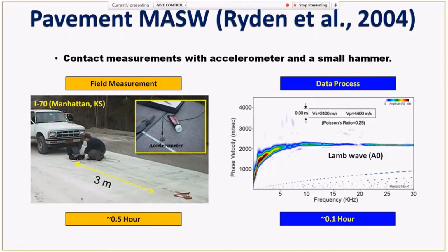So he could not use the conventional geophones that were used for ordinary MASW surveys, because geophones are good at recording only up to several hundred hertz of seismic waves. But here we have to deal with a few or several tens of kilohertz of seismic waves to resolve a very small scale with a very high resolution.